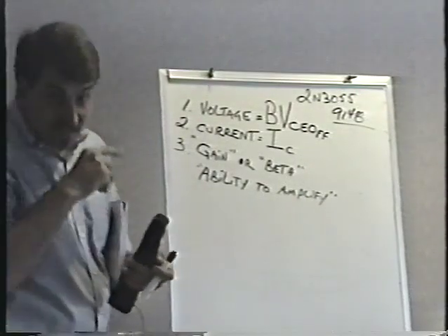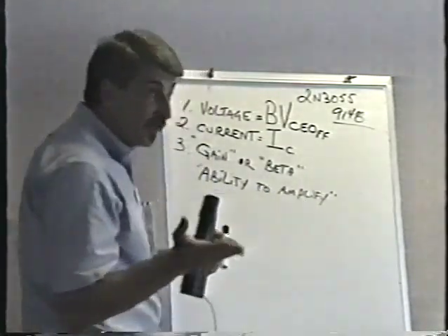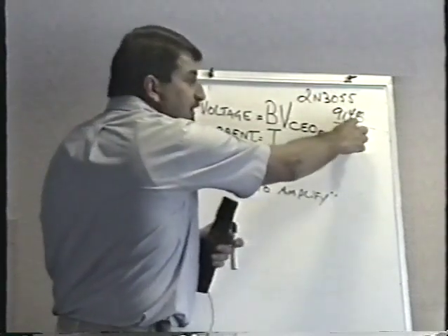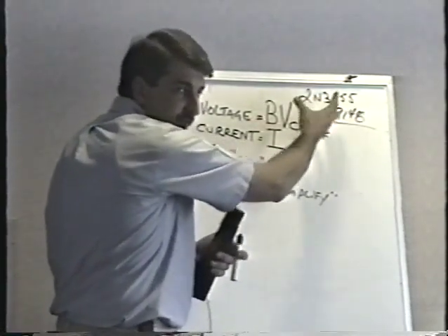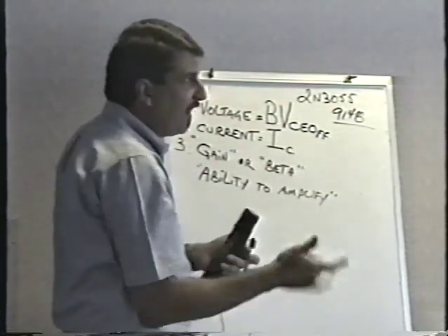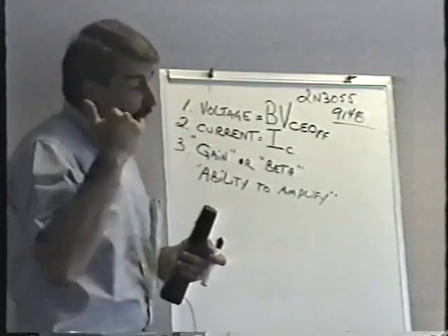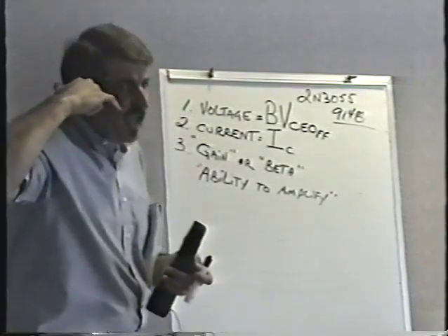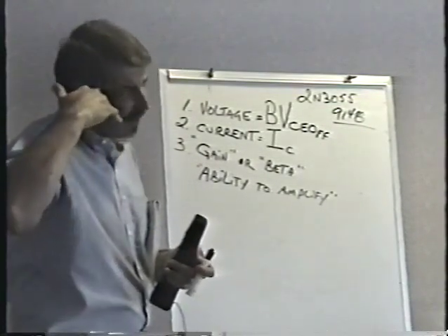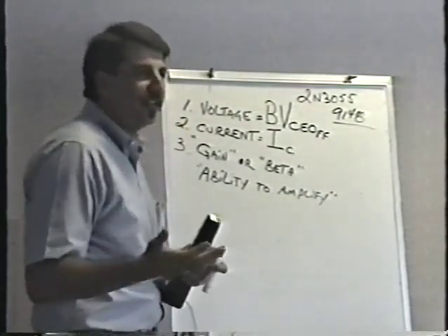Be careful about this. Almost every part has a date code on it, in addition to the part number. So if you see a number where the last 2 digits are 52 or less, and the first 2 digits look like a year, you're not looking at the part number. Every now and then I get a call from somebody: Randy, I'm trying to find this transistor. Yeah, what's the part number? It's a 9016. Oh, no such transistor. Yeah, man, I'm looking at it right here. No, that's a date code.